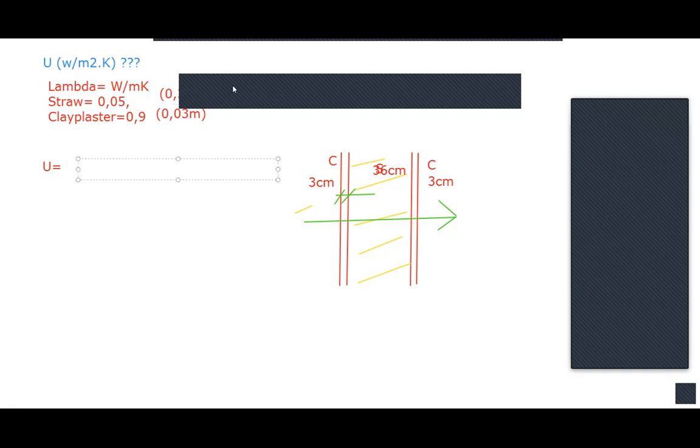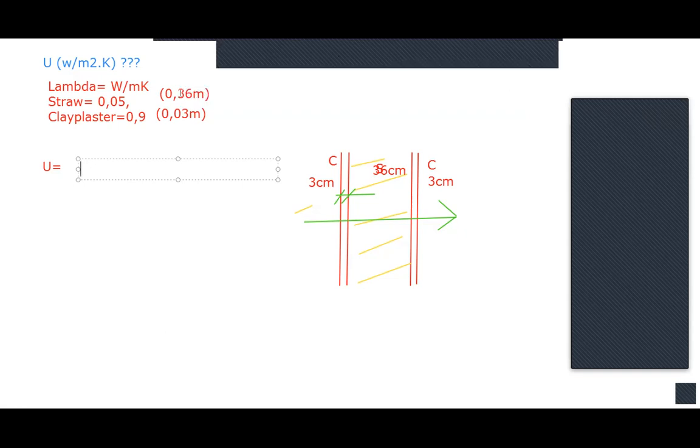So now you can look again at the units. We have meters, we have watt divided by meters times Kelvin, and in the end the heat transfer value is watt divided by meter square times Kelvin. So what we need to do is this meter square here is different. So when we simply divide two numbers, at the end it's the right equation here.